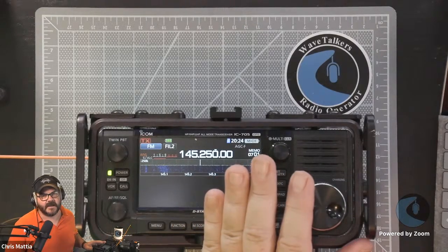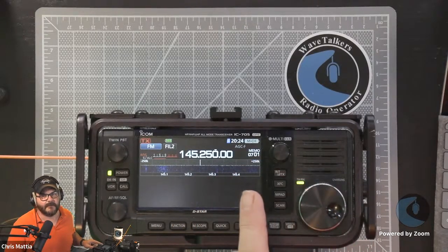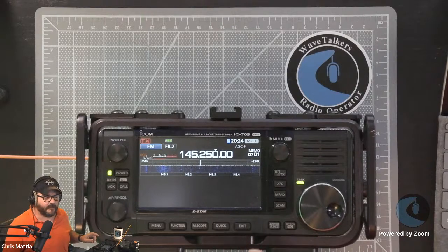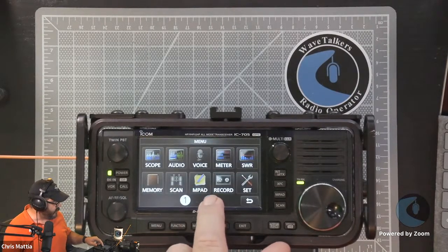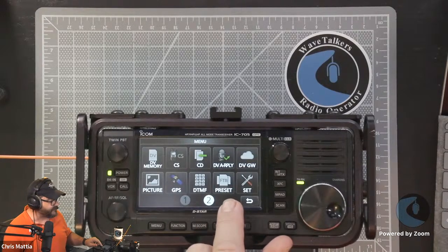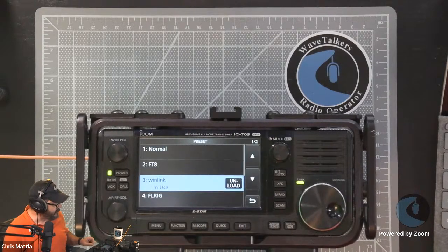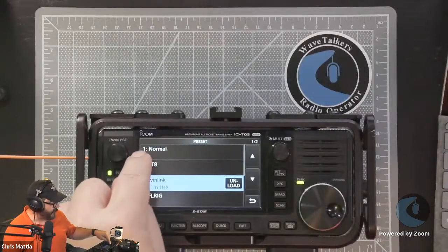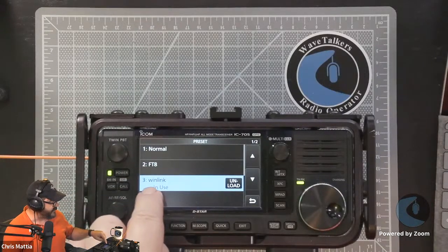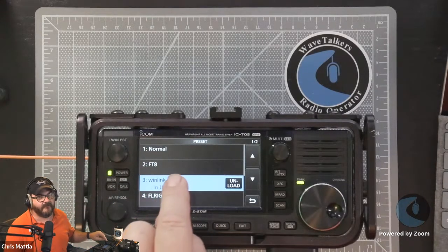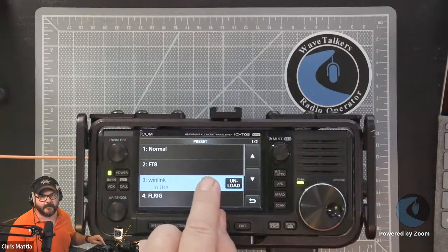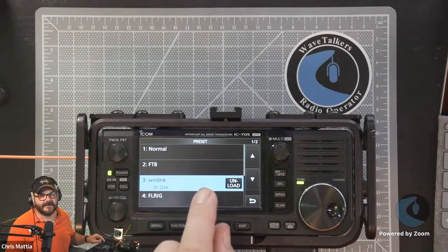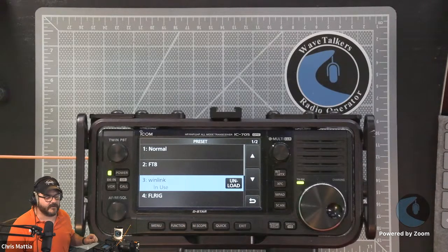A couple of things come to mind. The first thing is check and make sure that you're not using the pre-built FT8 setting. You get to that by going to the menu, over to the second page, and there are these presets in here. Tap on that preset. You'll notice that there's a normal mode and FT8, and I've even added a preset for Winlink specifically. The FT8 mode works really good for FT8, but it doesn't work as well for Winlink when you're trying to pass traffic. There's a slightly different setting inside of the radio to make that work.